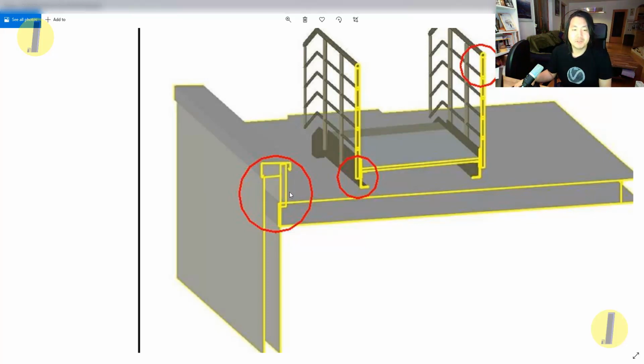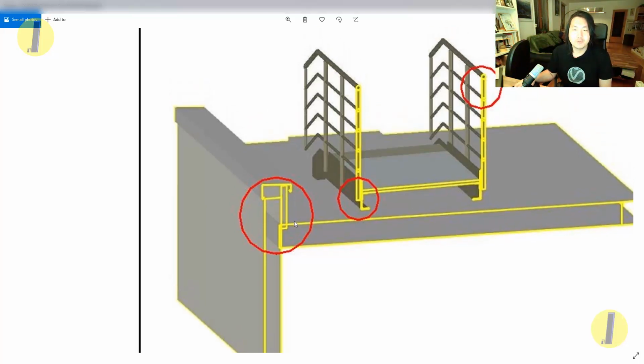But generally speaking, most BIM, building information modeling, projects are at the moment complying with LOG 300 or LOD 300, level of development. The level of information could be higher, but for level of geometry, in most cases they are happy with LOG 300.